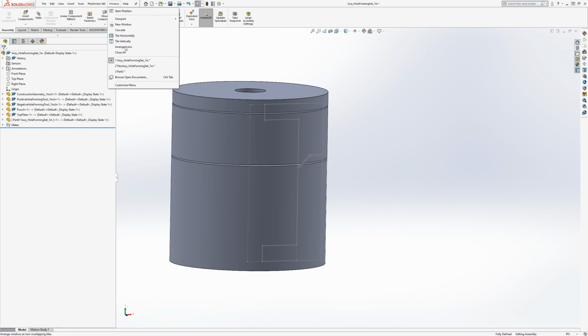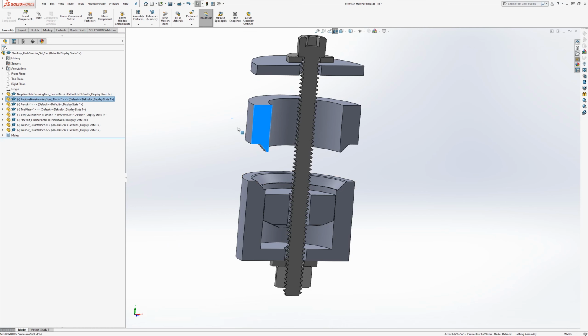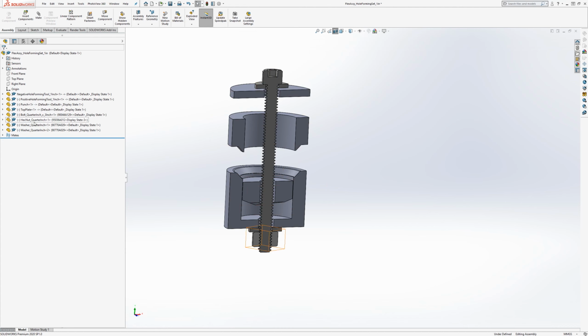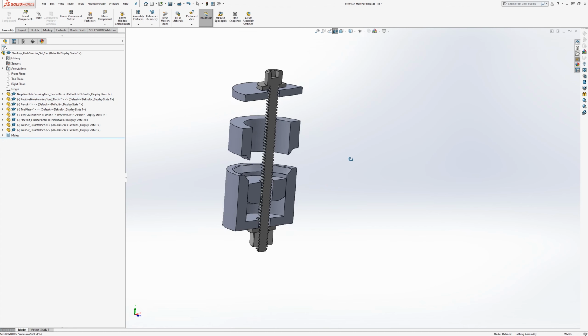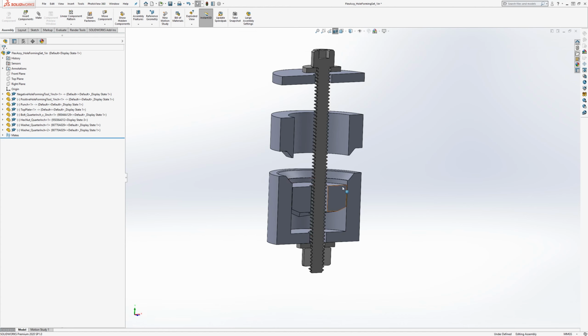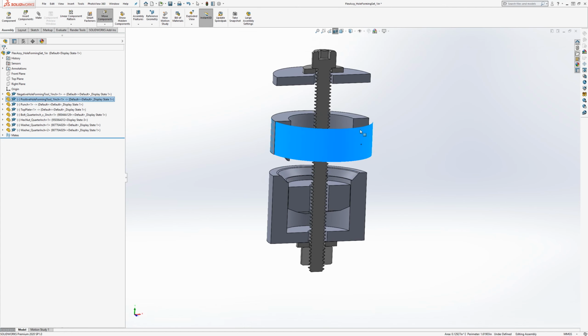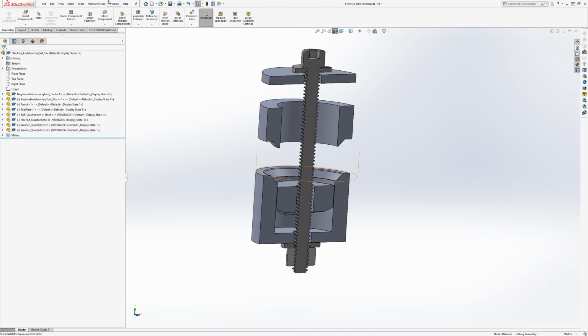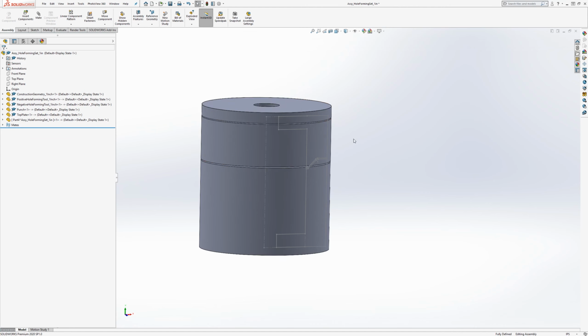Now, the way that we created this flexible assembly is by just creating a new assembly and importing these parts the way that they were saved from the other assembly and mating them into position in a way that they can move. So this assembly is not defining their shape. This assembly is an additional assembly that just lets us move them around, and this assembly won't change their shape. So how is that happening? Well, this assembly is the generating assembly.